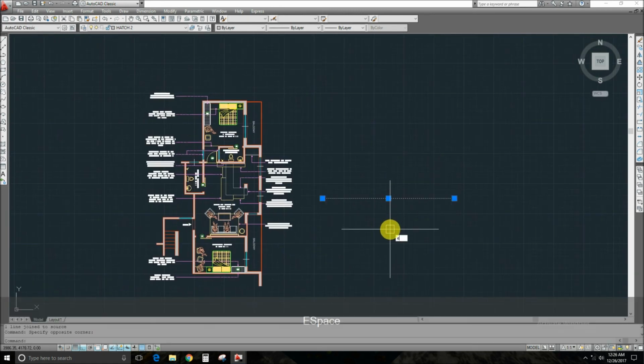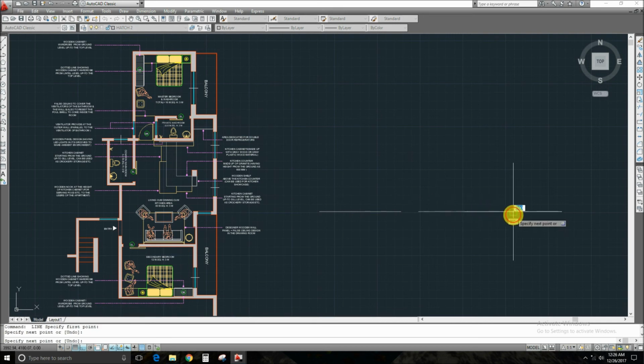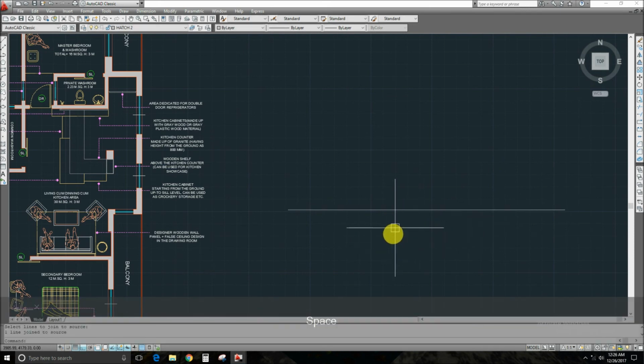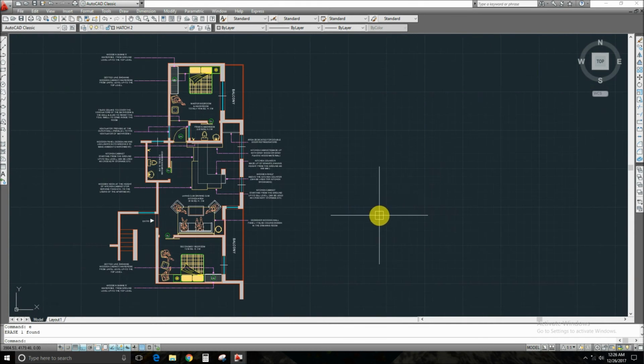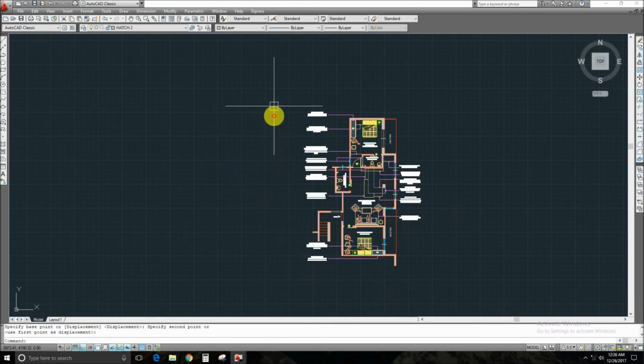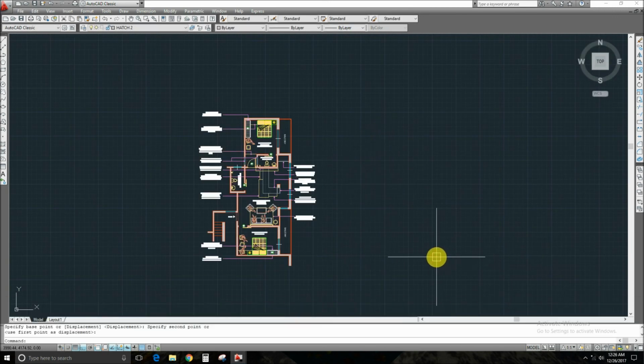So for the parallel lines and the lines in the same line, you can join it by J enter. By M enter command you can move any object where you want. By I you can insert a block or drawing into the current drawing.